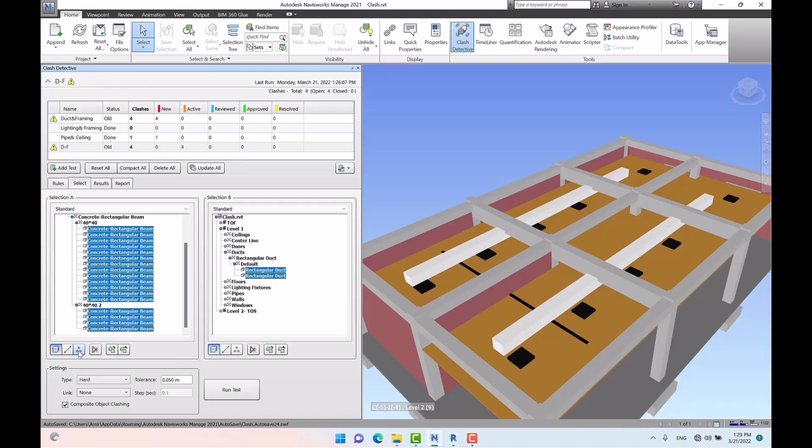And the next one is points, which includes point geometry in the clash test. Same as line, points are exported from AutoCAD too. But note that points and lines are not transferred from Revit to Navis, only the geometry of your objects is going to be exported to Navis, but the points and lines never. And selecting points and lines is not necessary.